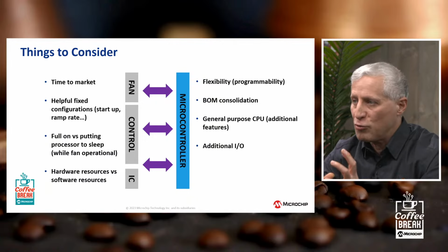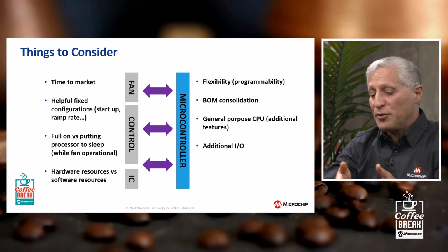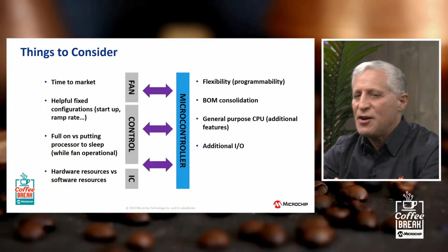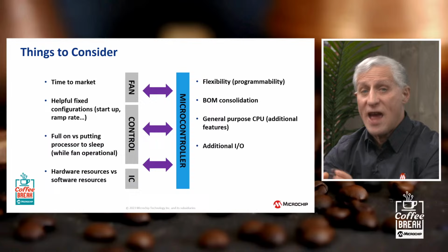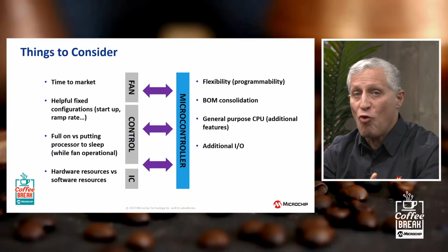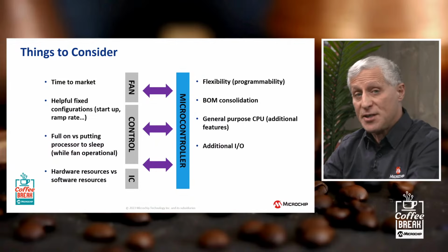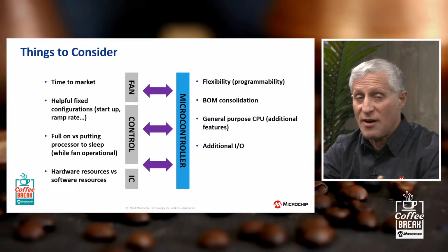And then also your startup, right? We're overcoming the inertia of the motor, and we've got some built-in setup configurations for that. Moving down the list, something a little more subtle is being able to put your entire system to sleep. We have a fan controller IC that runs the fan control; once you set it, you can forget it. The rest of your system can be put to sleep, and you can wait for the alert from the fan controller IC.